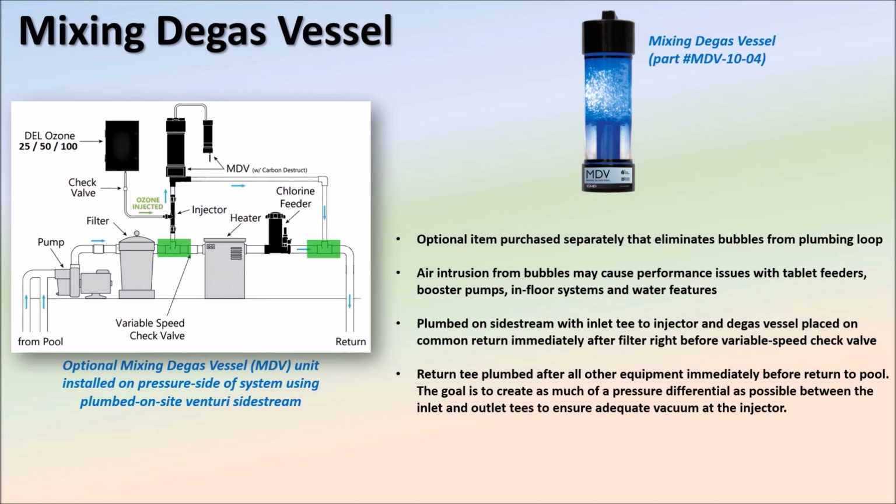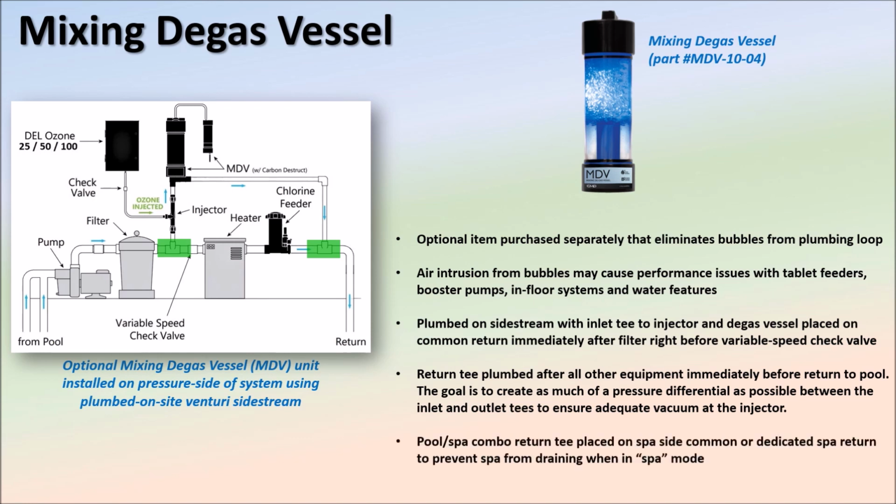On a pool spa combination with a spa overflow, place the return tee on the common or dedicated line that feeds the spa overflow to prevent the spa from draining when in spa mode.